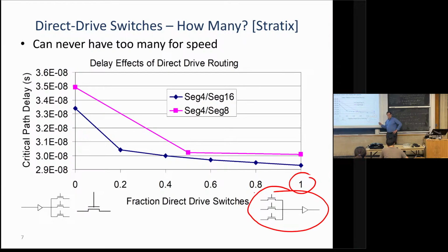And again, it comes with that limitation that I can only have one place where I drive a wire, because I can't turn this off. So if I put another buffer on it, they just fight, right? I haven't made a routing wire, I made a power waster.